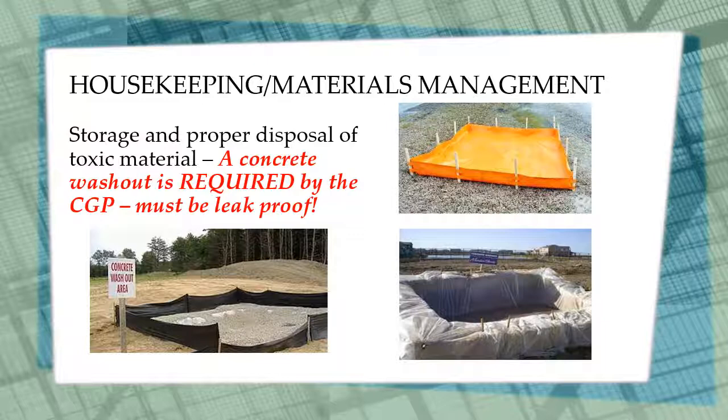Concrete washout is extremely toxic to any kind of aquatic plants or animals. Concrete washout must be stored in a leak-proof container. This can be as simple as digging a pit and lining it with visqueen and surrounding that with bales.